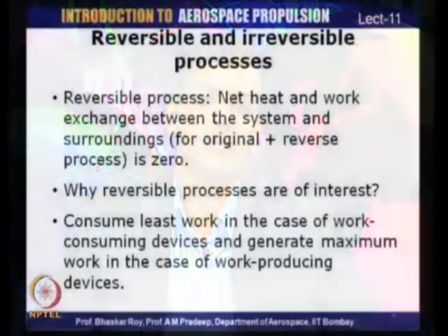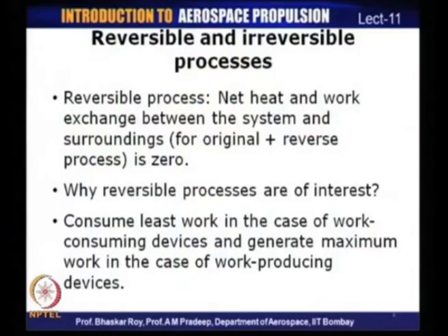As I just mentioned, if you look at a work producing device like a turbine, a reversible process would give you the maximum work, highest work, and consequently you would have the highest efficiency possible if the process being undergone is a reversible process. So, that is why reversible processes are of interest to us, at least in the thermodynamic aspect of the process.